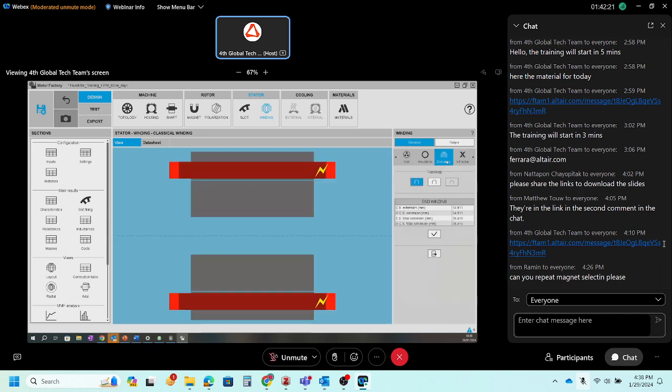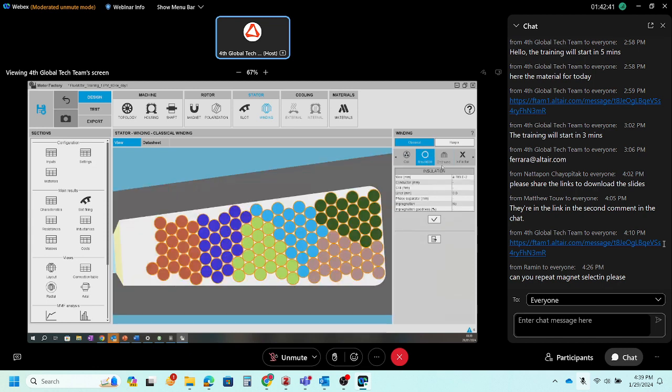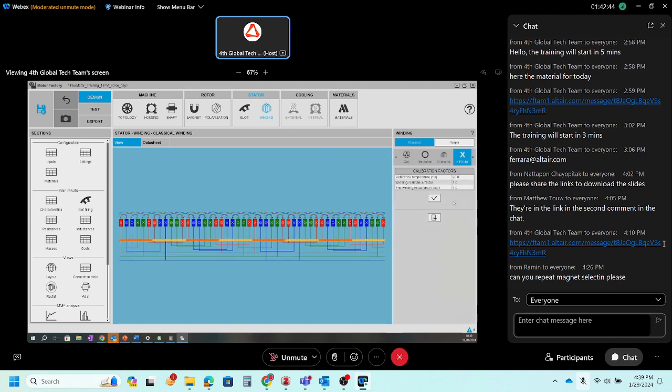And about the end winding, it's quite useful to define them for the thermal study, because the end winding geometries can help us to achieve accurate results in the thermal analysis. But for the moment, we can leave these 3 tabs as default. The X factor contains just some factors that we can consider along our design process.